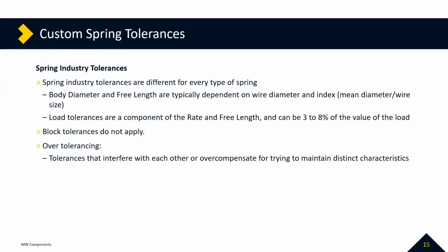So you're left with a space that you have to have a spring assembled into, and you're running tight on your own tolerances, and stack ups are creating less and less room. But keep in mind that as you design this spring, there are specific manufacturing tolerances that need to play a role in how you design it. And they vary for different types of springs.